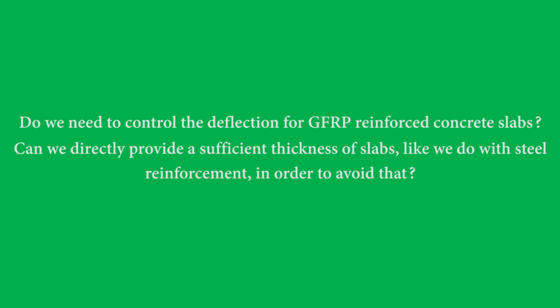In my calculations in the presentation, I didn't consider the serviceability limit states. I just wanted to give you an idea of the shear capacity, but for sure sometimes the serviceability limit states are controlling the GFRP behavior. So for sure, if you are going to use this for real field applications, we need to check the deflection.